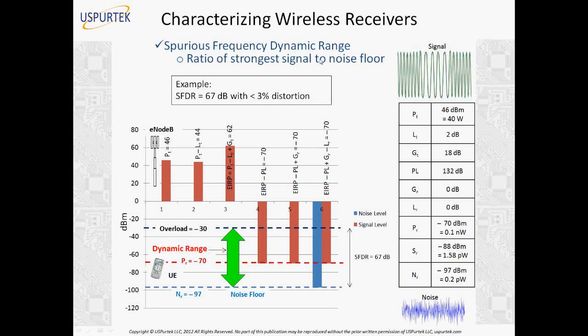Because when the signal grows to this level that causes overload, it causes a drift, and the signal overshoots into the non-linear region of the power amplifier. Those of you who are familiar with RF power amplifiers remember that if the input signal goes into the non-linear region of the amplifier, we'll have distortion, we'll have harmonics and all that stuff. We'll have spurious frequencies generated inside the receiver. So that is why this criteria is important here.